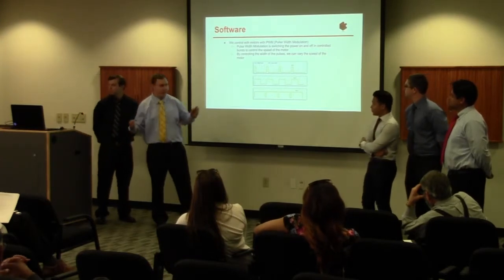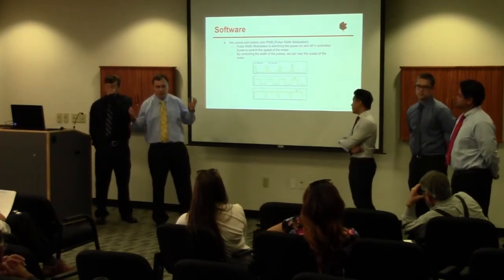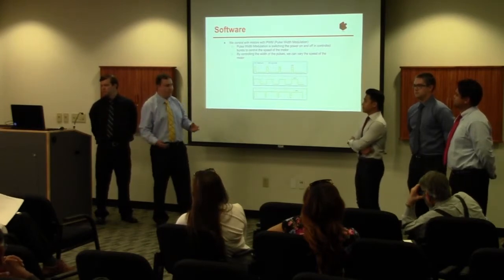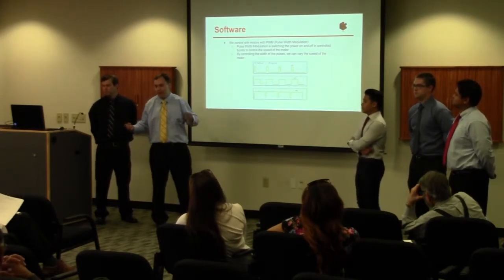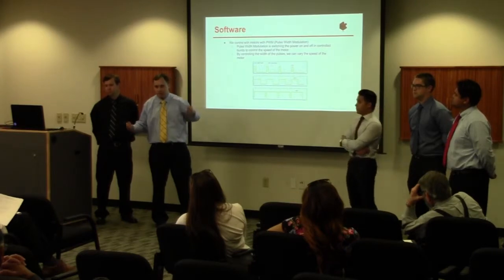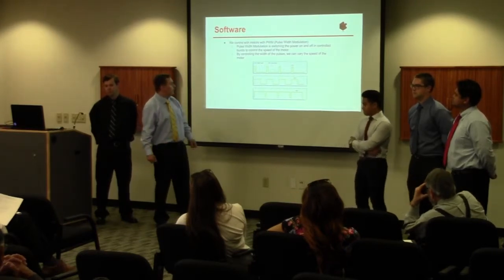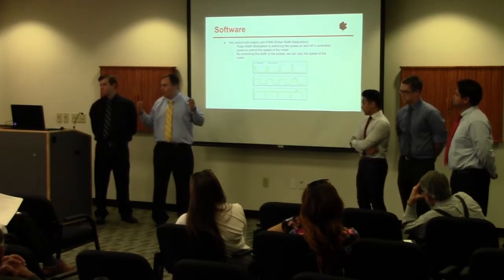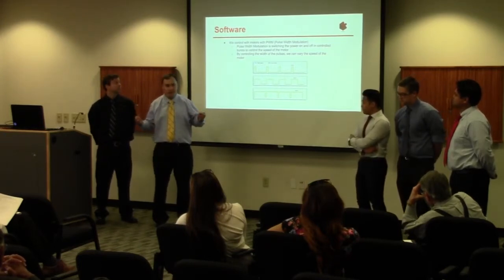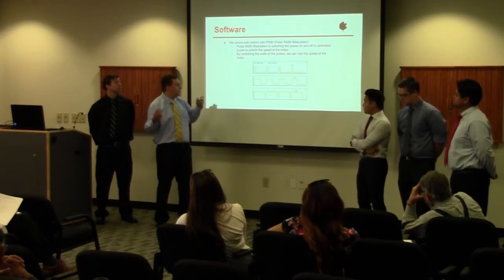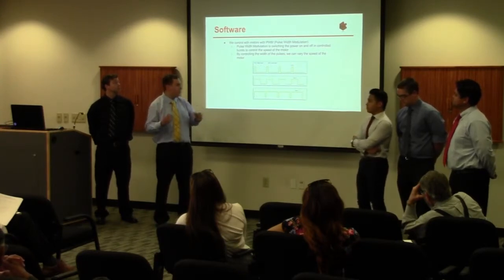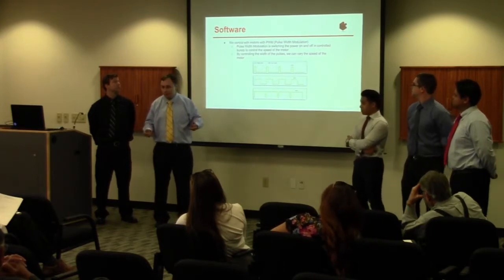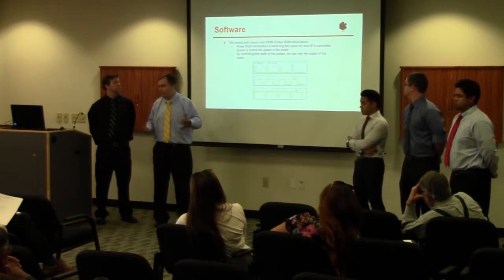And so you might ask, okay, well, how do we actually control the speed of the motors now that we know how fast they're turning? We can't exactly take the 7.3 volt battery and just raise and lower the voltage as we please. So we use a technique called pulse width modulation. What that is, we're basically switching the power on and off in controlled bursts so we can control the speed of the motor. And by controlling the width of these pulses, we can control how much current flows to the motor and therefore the motor's speed. Next slide.